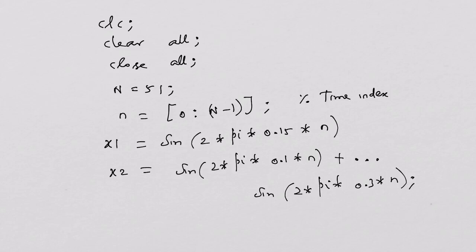And yes, there is one more third sequence, which is the product of the first sequence with 0.8 power n, its real valued exponential sequence. Third signal is a product of sinusoidal sequence with a normalized frequency 0.15 and a real exponential sequence, right? So we have created it.